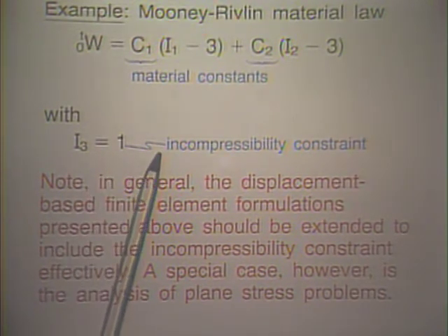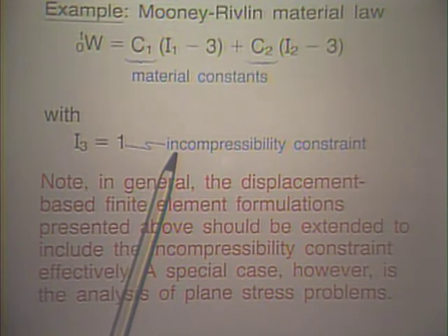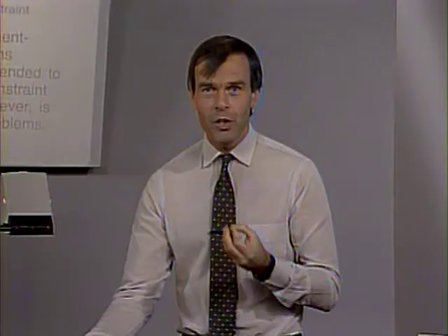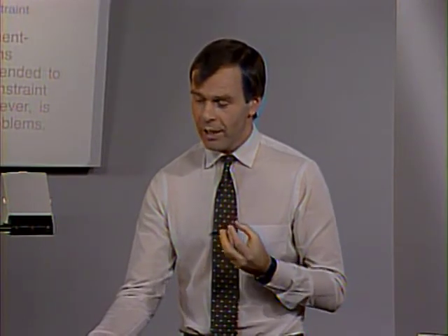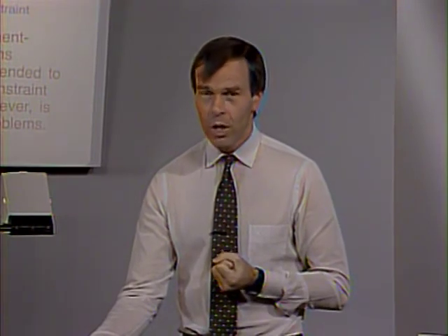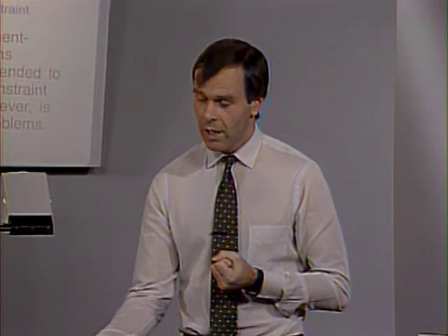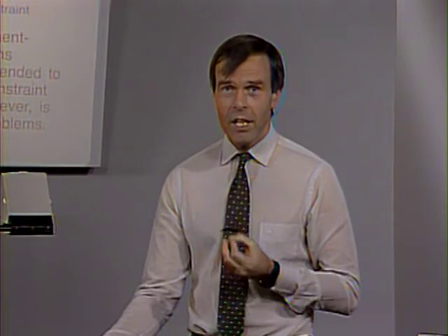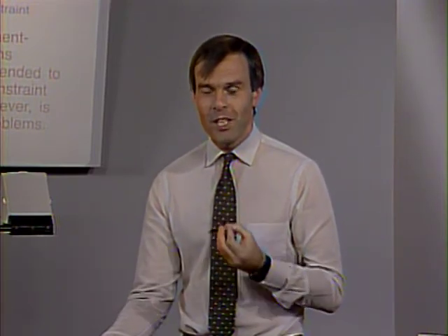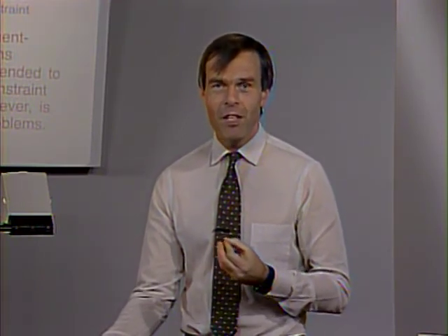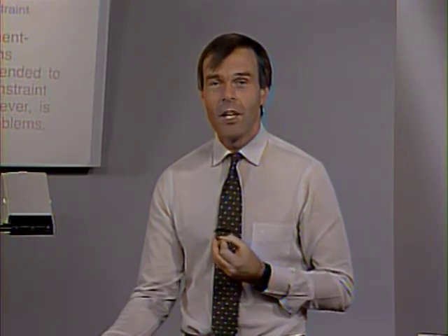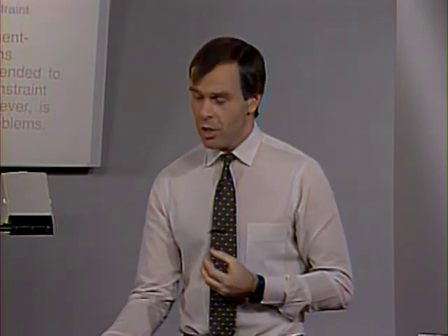Of course rubber is an incompressible material, at least almost an incompressible material, and is modeled as an incompressible material, and so we want to have I3 equal to 1. In general, if you deal with incompressible materials, it is effective to not use the displacement-based finite element formulation the way I've been discussing it in the previous lectures, but to amend that formulation.